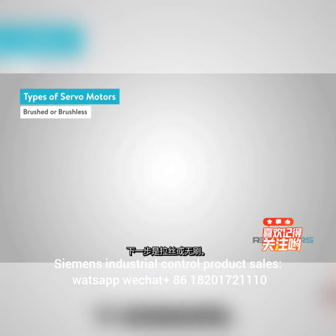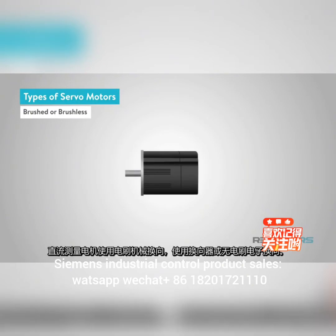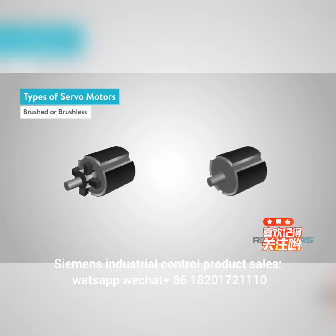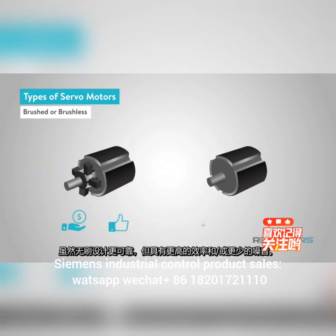Brushed or brushless is the next step. A DC servo motor is commutated mechanically with brushes using a commutator or electronically without brushes. Brushed motors are generally less expensive and simpler to operate, while brushless designs are more reliable, have higher efficiency, and are less noisy.